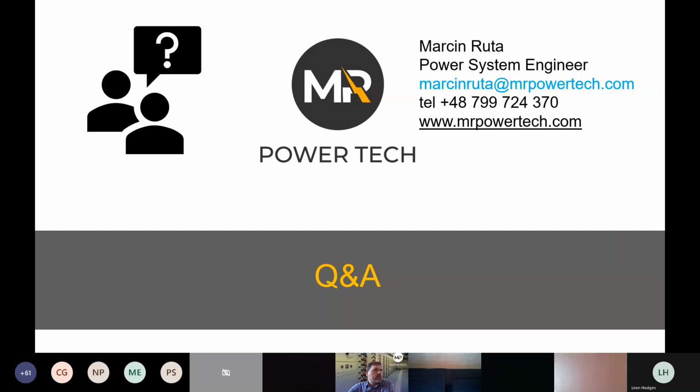I know there are infrared monitoring systems installed within the switchboard joints area to monitor heat spots to identify early failure. How do you see such a method beneficial to arc flash study? Technically it doesn't have anything to do with the arc flash study, so it will have no influence on it. Maybe it influences the risk assessment, or maybe not even. It will not change anything. It will just allow you to identify an early stage of failure, which is very good to have.